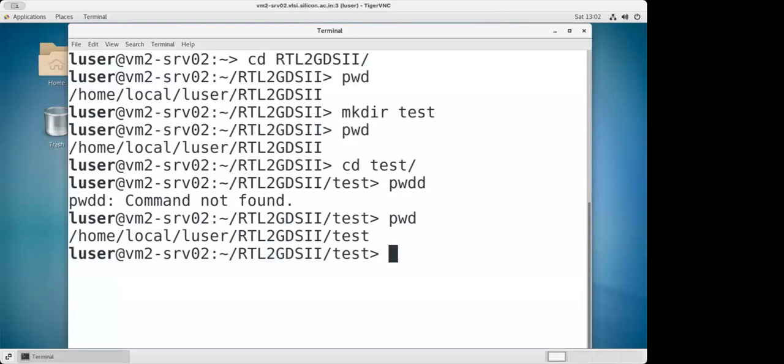Okay. So now let's try whether you are able to invoke the tool or not. We'll do it in the reverse direction. You're supposed to be in this test directory folder. Now do pt underscore shell. Type this in small letters, pt underscore shell, and enter. And then you have to wait for some time. Wait for some time, it will give you a terminal. I will show you that one. Even it is taking time for me. That's good.